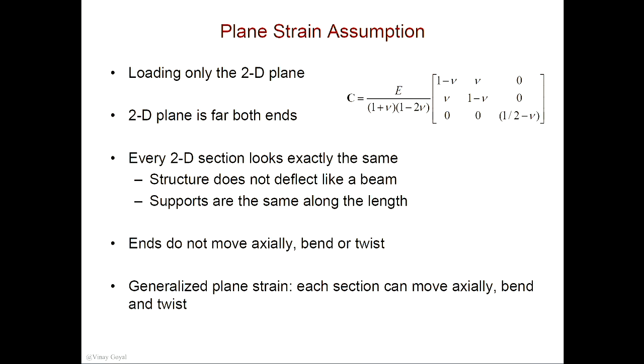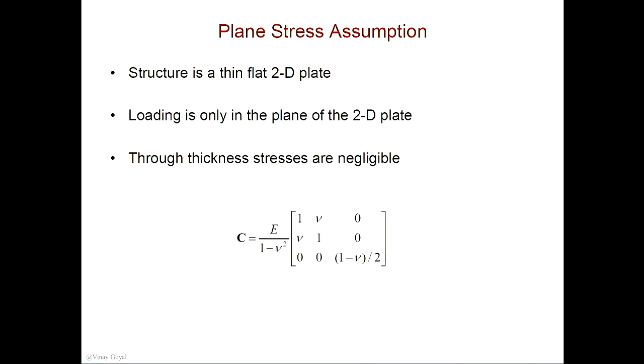It's incredible. You can apply bending and out-of-plane loading, not just in plane. So they were able to extend that formulation further. I've used that formulation quite a bit, so just keep that in mind. This element here is the CPE4 in Abaqus for quadrilateral, and for plane stress it is the CPS4, I believe.